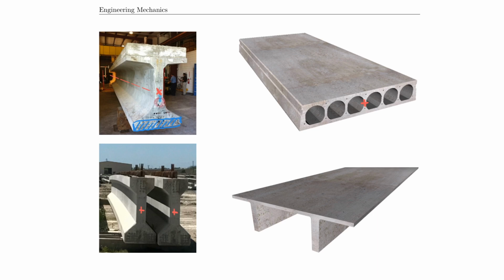In fact, it's also true for my double T-beam here. You see these double T-beams a lot in parking garage structures and so on. They are very comfortable structure components because they are very easy to fabricate and very easy to transport. And as you can see, they have two legs, so they never tip over. They are easy to store and they're easy to install. In fact, engineers use these like Lego blocks.